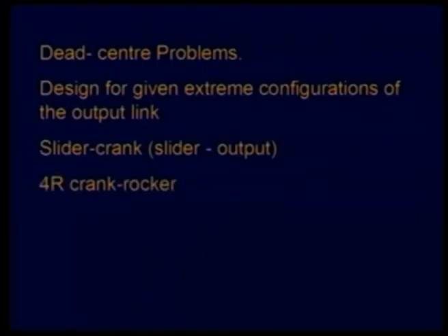Next we discuss what we call dead center problems. That is, we have to design linkages for given extreme configurations of the output link. We can do it for the slider crank mechanism with slider as the output link, and also for 4-bar crank rocker mechanism where obviously rocker is the output link.